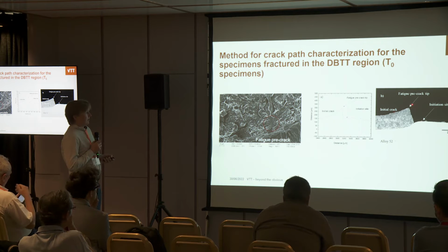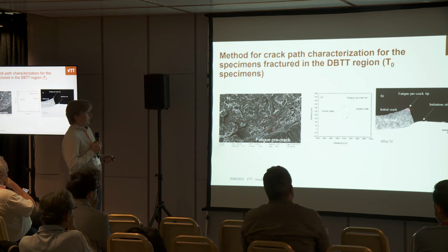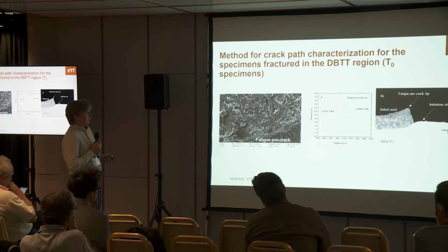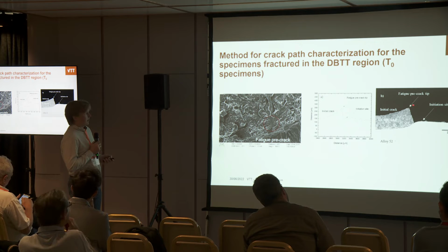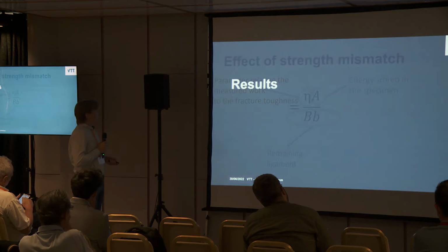And then here you can see that confirmation. You see that's a fatigue pre-crack, and the initiation has occurred somewhere close to the fusion boundary. And this type of jump happens in all of the specimens.